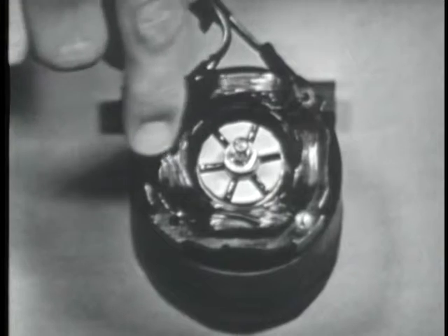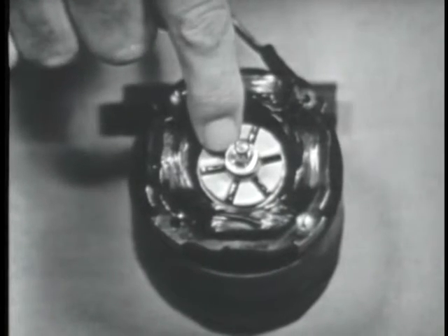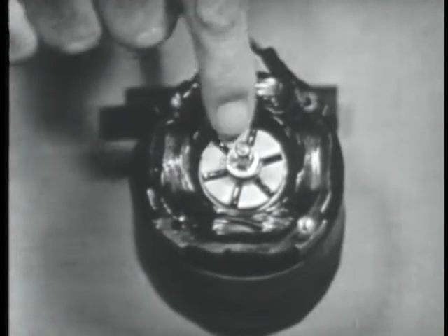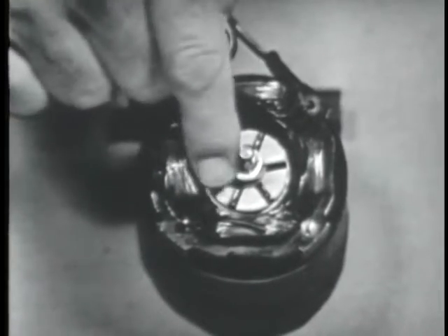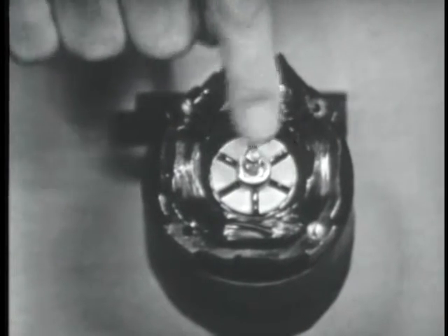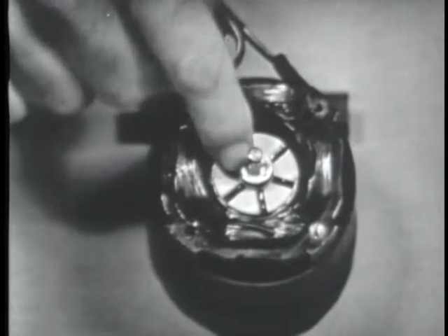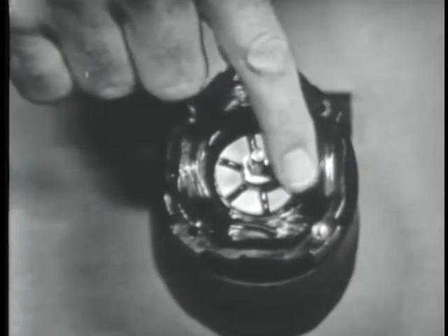Right. Okay, so the rotating magnetic field then induces a voltage into the conductors of the rotor, causing it to become an electromagnet. It exhibits a north and a south pole. The rotor turns at some speed determined by the load, both internal and external load. Now, the difference in speed between the rotor and the magnetic field is called slippage.